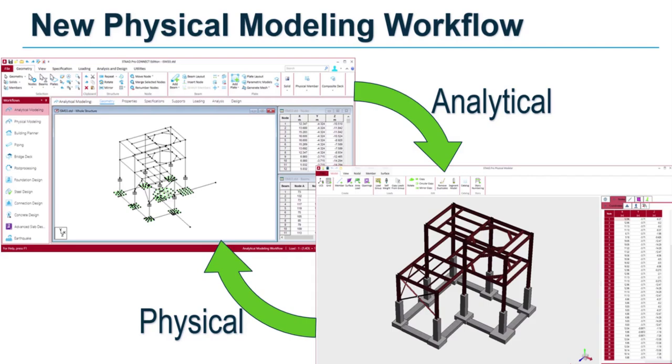Now, why do we need those joints and that mesh? This is just to discretize your model, to create more nodes where the response of the structure is calculated by solving the different equations involved in finite element modeling. But modeling that discretized representation is sometimes very challenging. For example, you need to maintain some parameters: the meshing should be proper, it should maintain a good aspect ratio, there should be a well-defined shape, and connectivity should be proper.